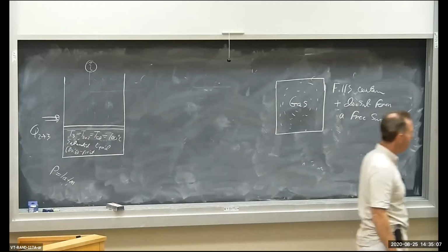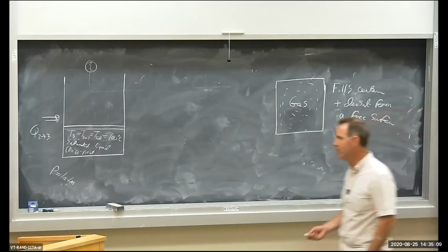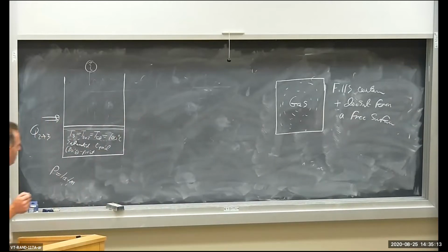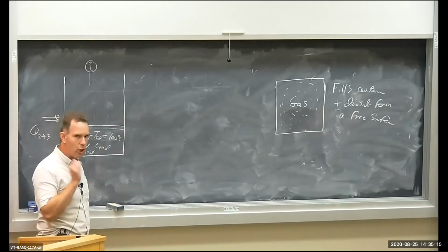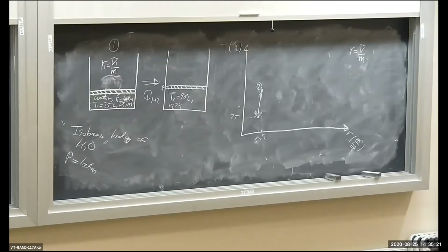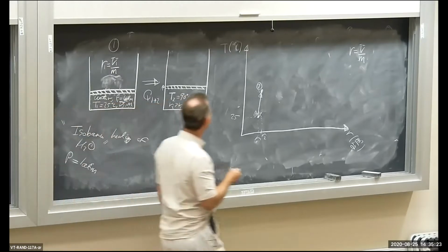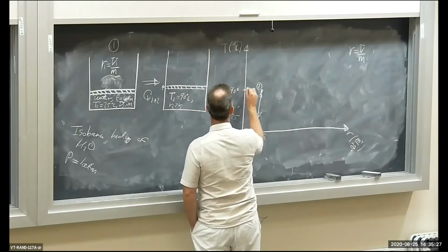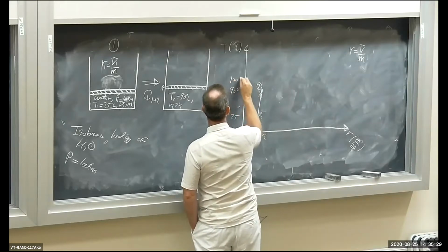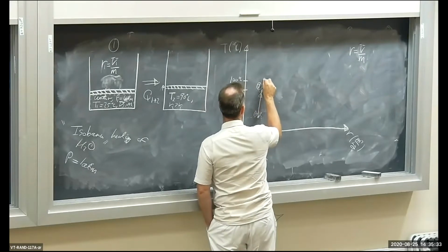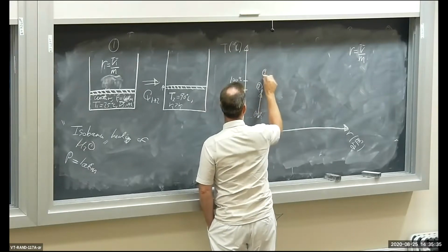So we're going to heat it up to 100 degrees C by adding just a little bit more heat. It's liquid, but it's saturated liquid, just ready to boil. So let's put that additional state number 3. This was 90 degrees C, and now I'm going to go up to 100 degrees C. Okay, so that's state 3.